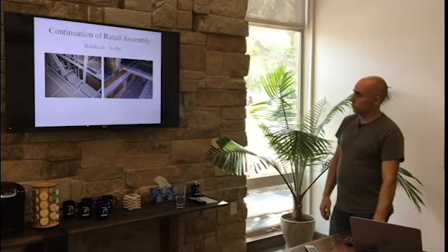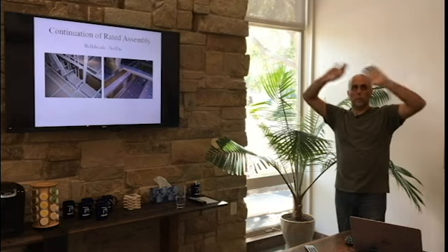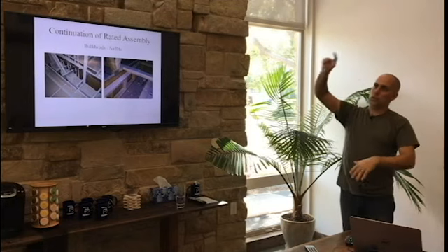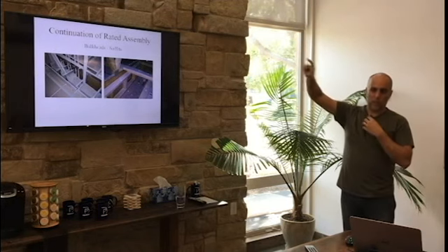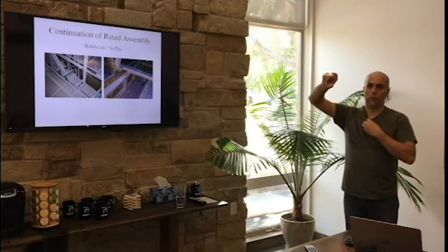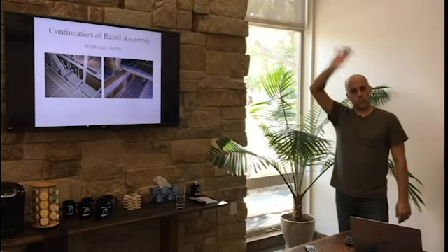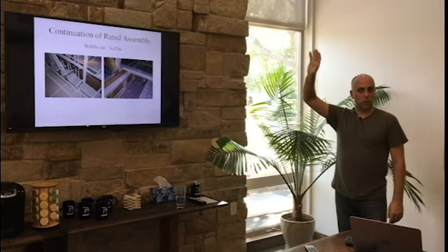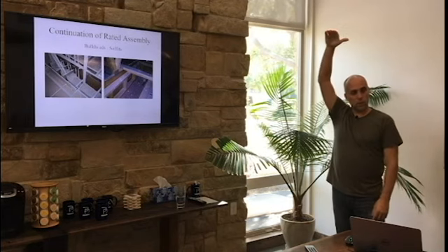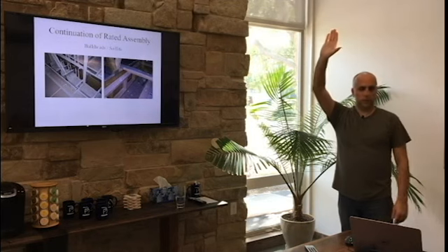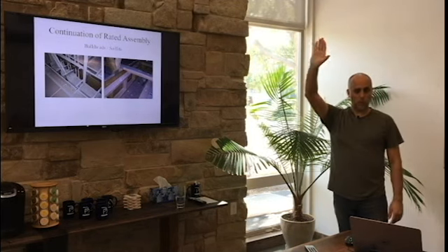So if I'm standing in the living room in a big facility and I'm looking up, I see walls and I see a double top plate, and then I see trusses on top of that double top plate, but the ceiling is still another 3 feet above. I have bearing wall and roof ceiling in the same plane. Well, they've got to be treated according to the assemblies.